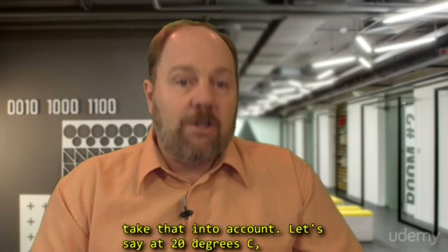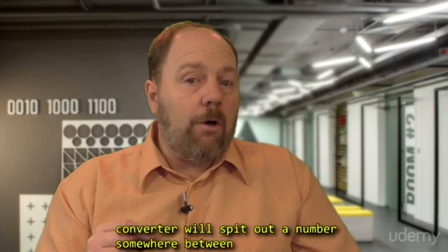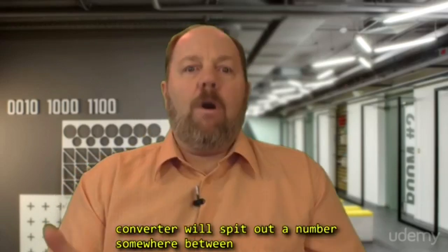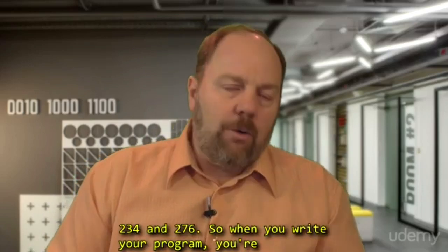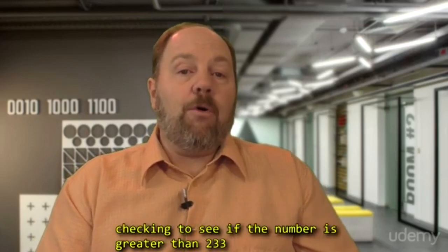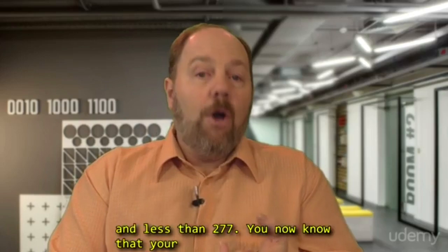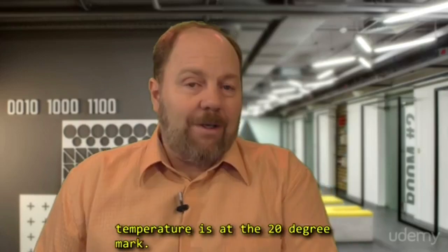Let's say at 20 degrees C, your thermistor experiments showed that the A to D converter will spit out a number somewhere between 234 and 276. So when you write your program, you're checking to see if the number is greater than 233 and less than 277. You now know that your temperature is at the 20 degree mark.